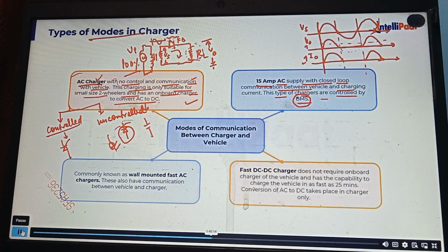It is not monitoring. They only monitor the percentage, or SOC, we can say, state of charge. If the state of charge is 100%, they will simply cut off, or the battery will not be charged beyond that particular voltage. That's all. But there are certain advantages to controlling the battery parameters so that the battery is not overcharged or over-discharged. And this battery management system can be integrated.